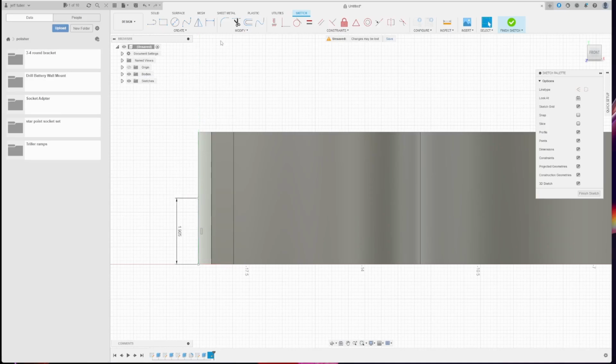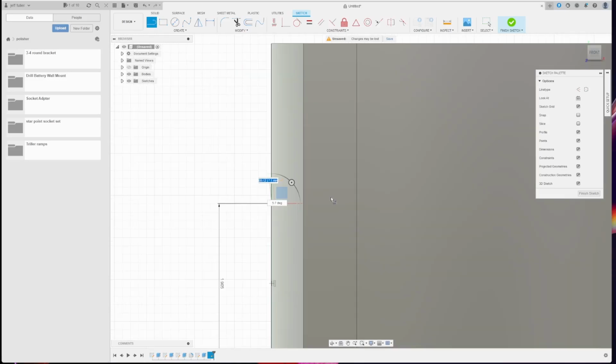This will tell us our center, and then I can pick how far in I want to put this hole, and I said it was about 80 thousandths, and I probably want some material here, so let's go 0.08 divided by 2 and then enter IN. Back this out here.